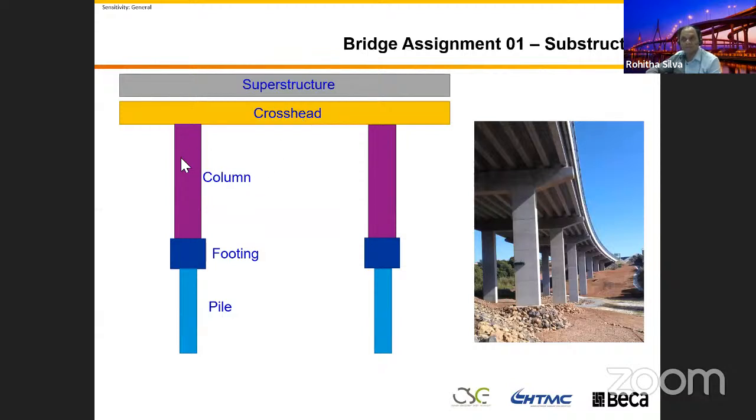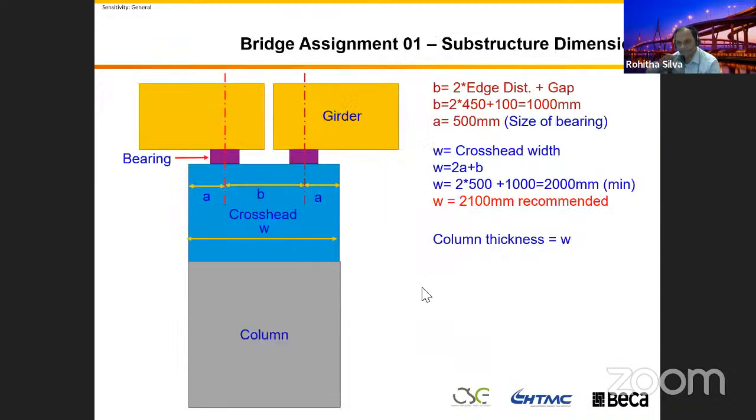The column dimensions are more or less the same. When you play with the architect, if the thickness is T, it should be at least 2T, or 1.8 something T. You can't go otherwise T and T, otherwise it should be square. It should be tapered in a nice way. You can play around in many different ways.